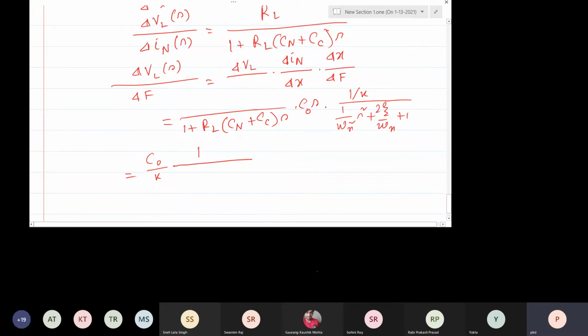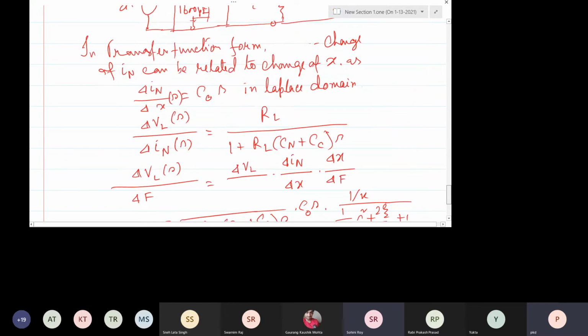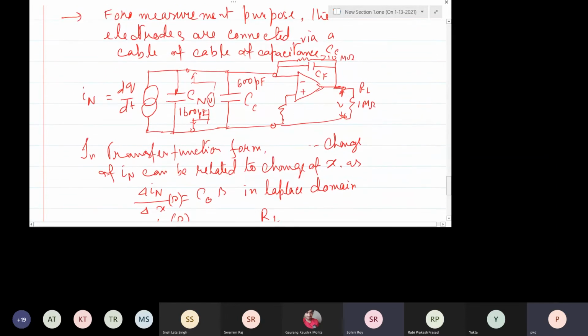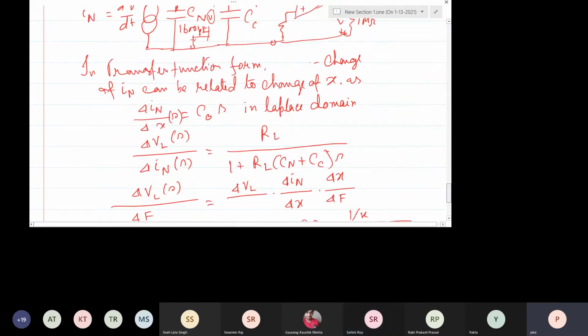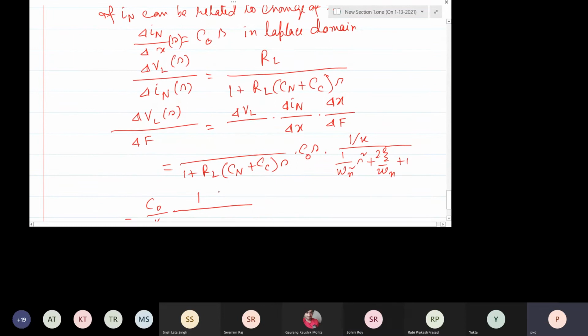Even current is measured electronically in most cases through an equivalent voltage measurement. So the voltage that it is measuring is proportional to the charge, and that is proportional to the force? Yes. So basically, this output VL is the voltmeter output, and this one is the input.